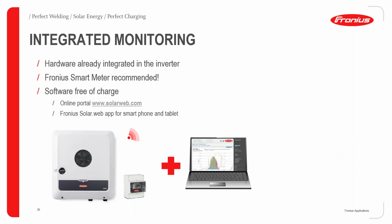Of course, you can buy a light version of a Snap inverter. Still, we always recommend having a full version with the data manager card in it, because it is very important to monitor the inverter's production remotely. This allows you, for example, if you want to do an update, to do it remotely. Troubleshooting is possible remotely once you monitor this inverter in the Solar.web. We also recommend using a smart meter, because the smart meter is the key which is going to help you for future